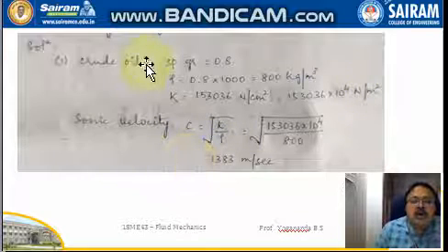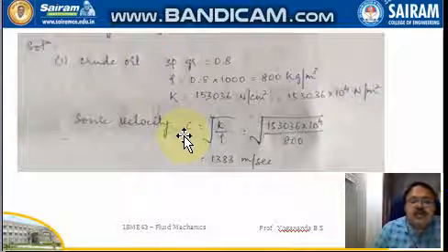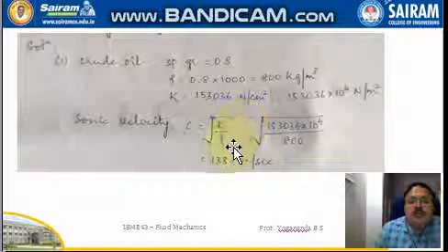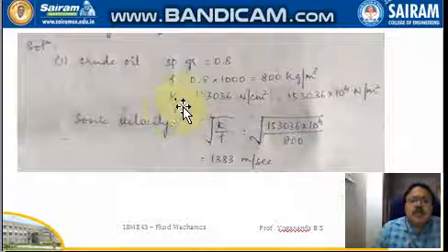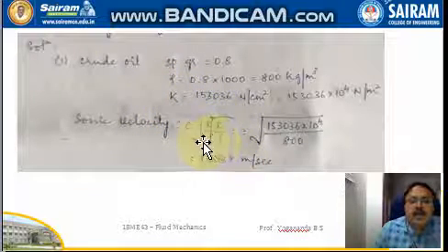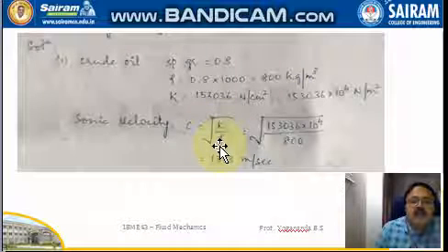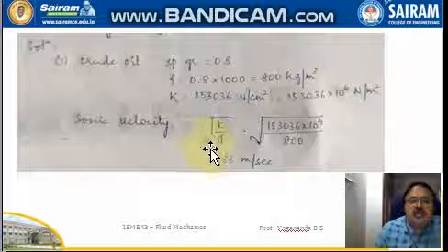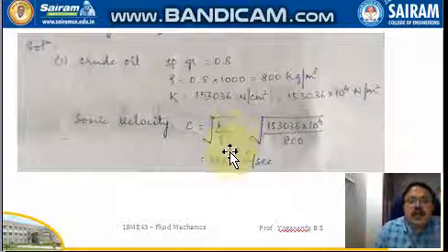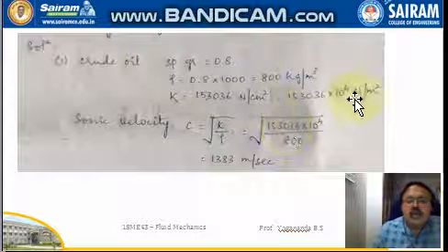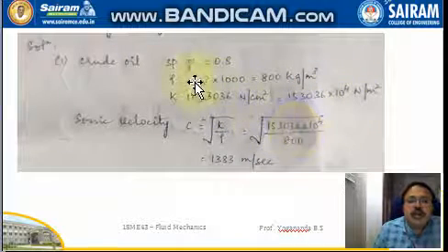Now for the crude oil, the velocity of flow is given as square root of K divided by rho. Since bulk modulus is given in the statement of the problem, we are taking the equation of velocity of the compressible flow with the bulk modulus, that is square root of K divided by rho, where rho is the density and K is the bulk modulus given, substituted here.